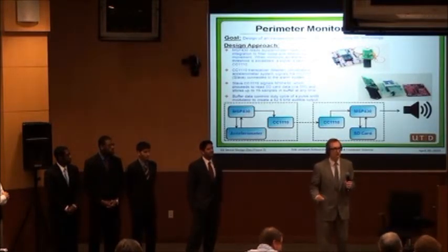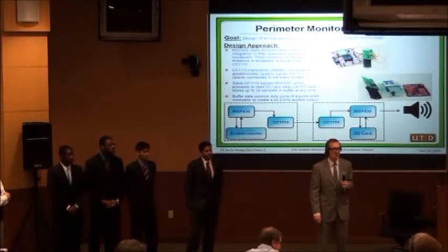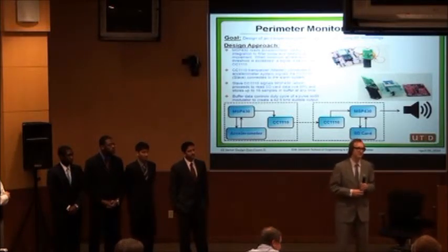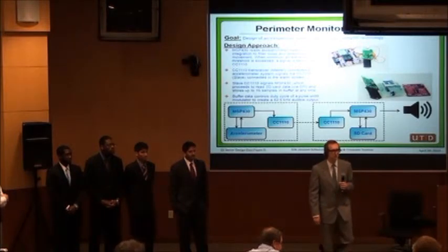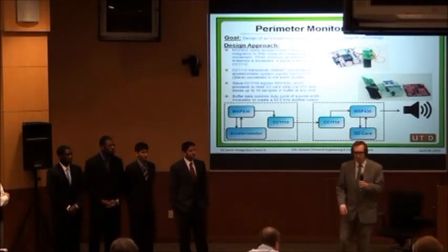Let me be real clear. You made the statement this is cheaper than commercial alarm systems that you can buy. I happen to know DSC sells wireless sensors that mount to the door that use accelerometers. The sensor costs about $30. And it runs off a CR123 battery and it will last about 2.5 years on that battery. And that transmits over 433 megahertz. It's got a range of about, and a receiver that costs about 45 bucks that will monitor that. So how does your system compare to that?